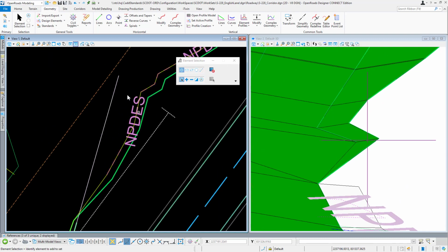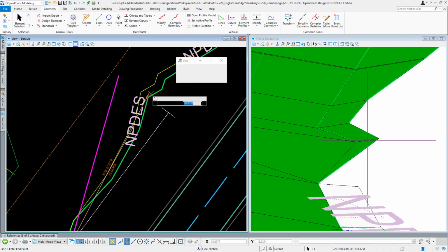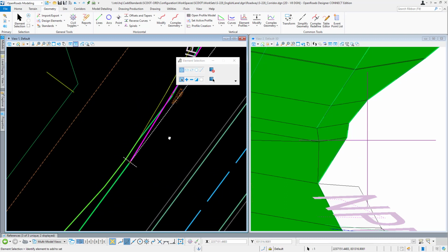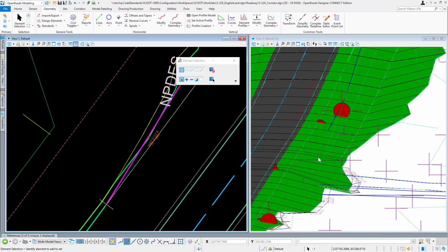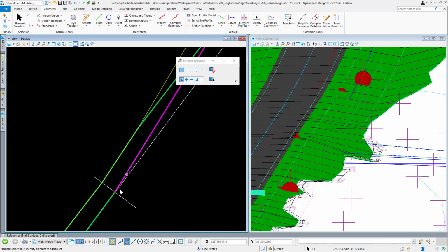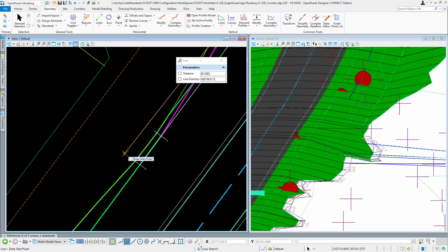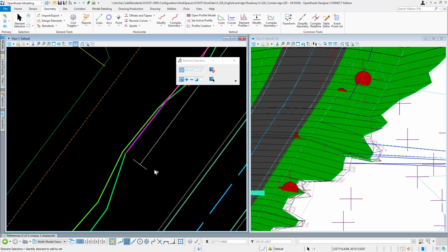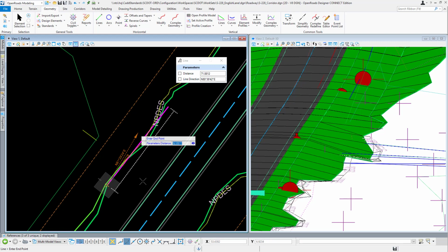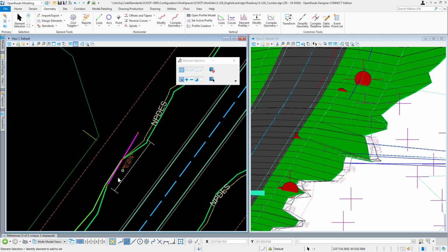So we can come in here. If we don't want that ditch to taper out in that direction, we can grab our line and move it in. There we go. Looks like we're going to end up needing guardrail down here anyways, so this is just an example to show you what this software can do. If we kick this line out here, I'll show you something. We can see it even juts out. It keeps that same shoulder slope and just sends it on out. It makes a nice transition in there for us. But that is a point control that you could do. It'll come in handy.